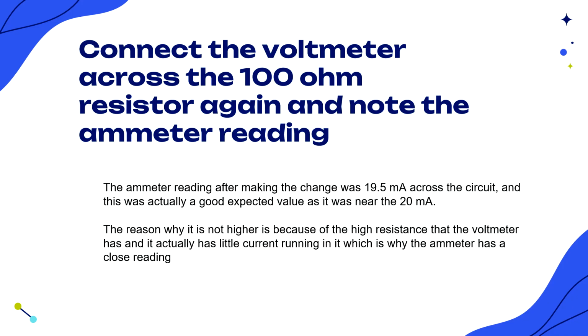Connect the voltmeter across the 100 ohm resistor again and note the ammeter reading. The ammeter reading after making the change was 19.5 milliamps across the circuit, which was a good expected value since it was near the 20 milliamps from before. The reason it's not higher is because of the high resistance that the voltmeter has, and it has little current running through it, which is why the ammeter has the close reading of 19.5 milliamps.